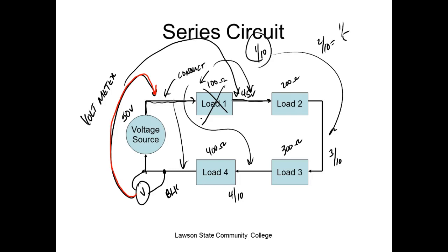So this is why, if you've got Christmas tree lights and you pull out one of them, you're going to lose what? You're going to lose a set of them because they're connected in series. But you plug those into 120 volts, and those light bulbs are not rated at 120 volts. They might be 3 volts because they all have the same resistance, and each one of them only drops the voltage that's required, right?